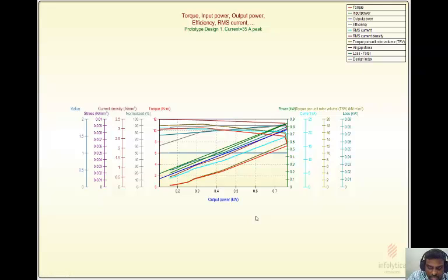As far as this design is concerned, we only intended to design the outer rotating hub motor for an output power of 500 watts for a rated speed of 500 rpm. The approximate efficiency we planned to achieve is 85%, which we satisfied by means of this software design.